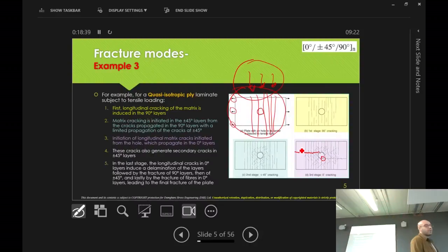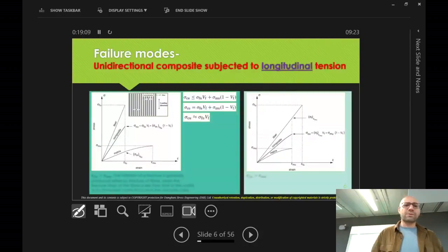So, yet again, this is a quasi-isotropic one. We've had 3 different failure mechanisms, and the loading and the configuration of the structure also determine this. In this case, we have a flat panel with a circular cutout, which is a structural feature causing stress concentration, and that determines in what mode it fails. Let's have a look at this one.